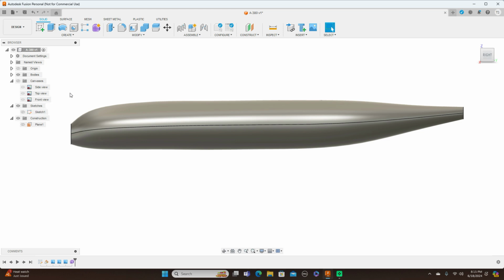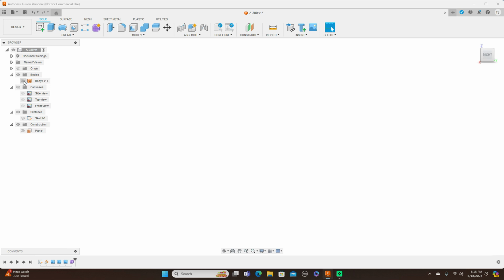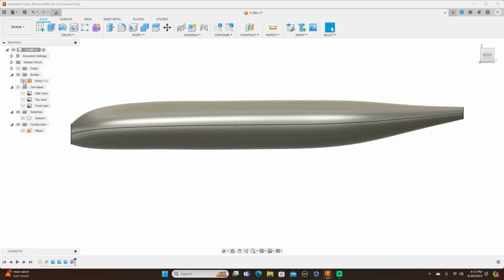So what we can do here now, since this is a body, come over here to the bodies folder, click this right here, and this is this body here. So we can turn that off by clicking this eye here, which turns that off and turns it back on.